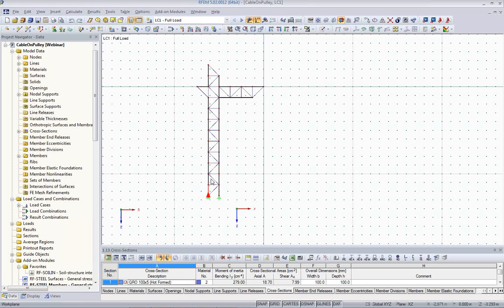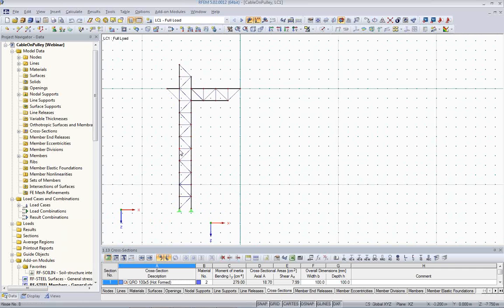If I model it with a regular tension element only, or with a cable element, then I have a fixed connection between the two ending nodes, and I have not this effect that the cable kind of slides around this node. So in RFEM, it's possible to model such a thing, and this was done due to a wish of a company that plants or sells cranes. They have this situation very often.